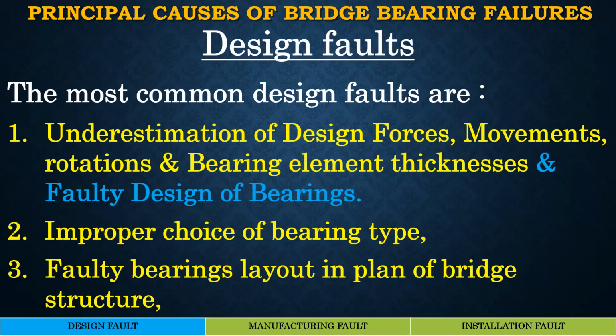Incidentally, the design of a bearing is done by two independent organizations. One is the bridge designer who is involved in the bridge project. He or she estimates the design forces, movements, and rotations, and prepares the bearing layout.